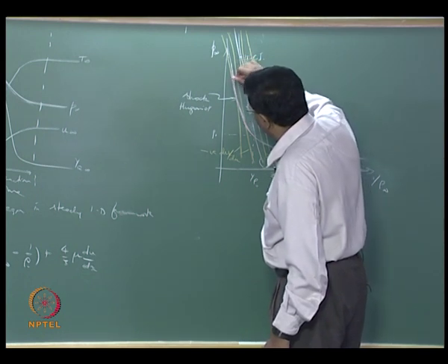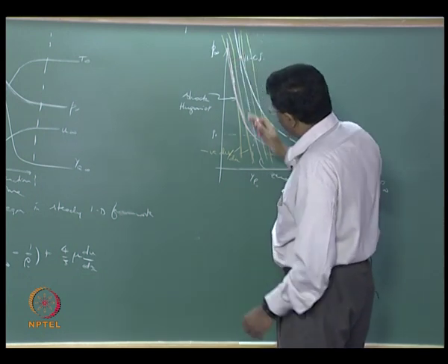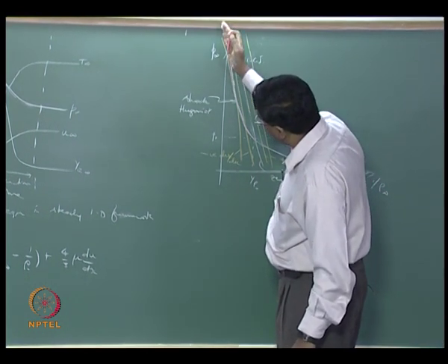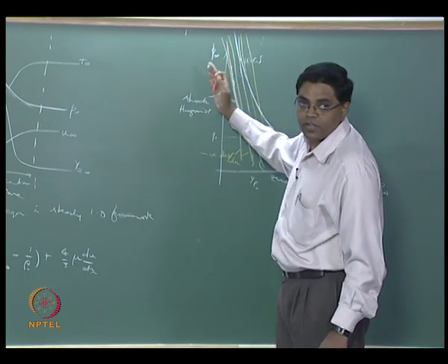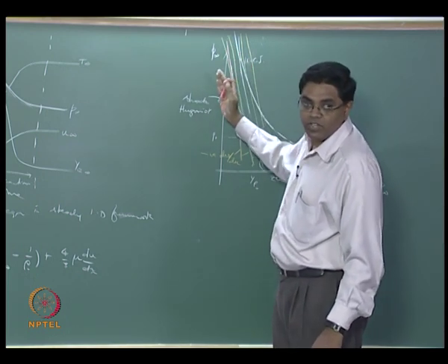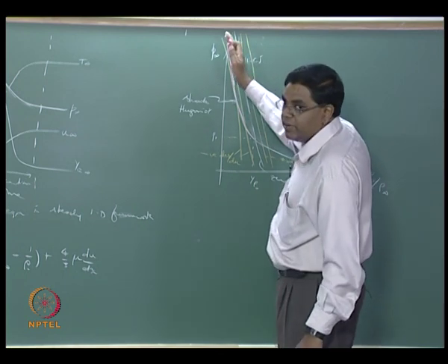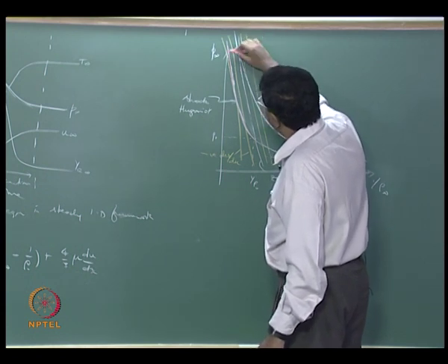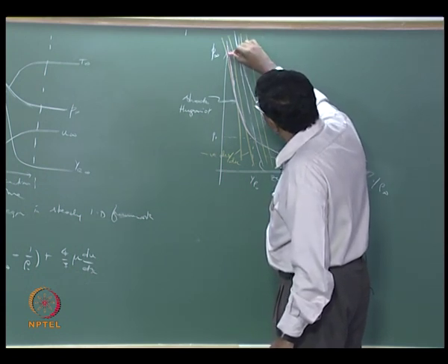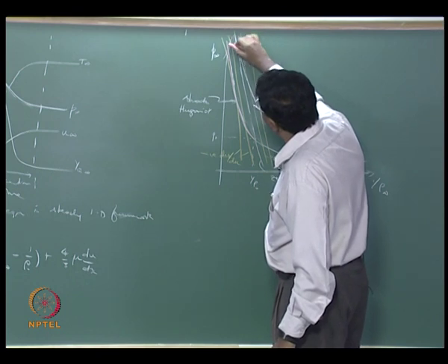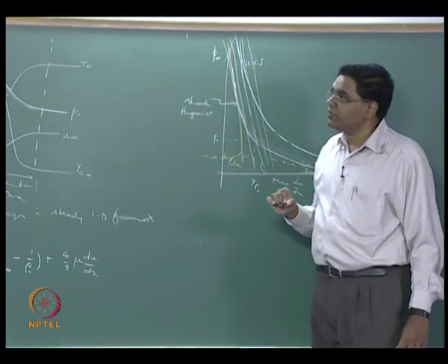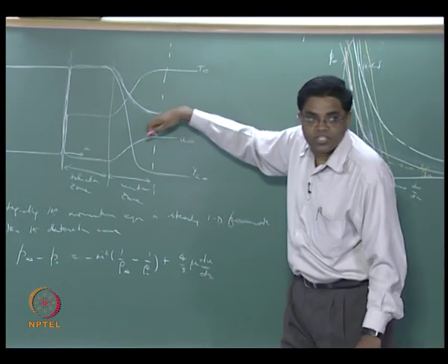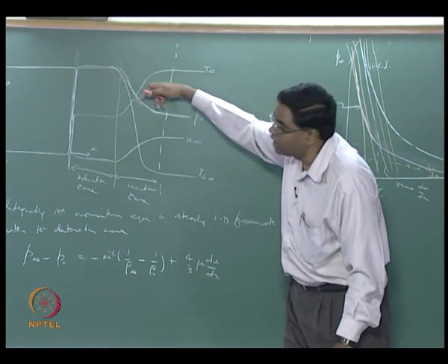That means your path would now go along the shock Hugoniot as much as possible. You see, the moment the shock Hugoniot deviates from the Rayleigh line, like in tangent Rayleigh with a negative du by dx, your du by dx begins to grow back to 0, and then it goes away from there and reaches your 0 du by dx, and then you have to go through the positive du by dx region, when the pressure begins to fall again.